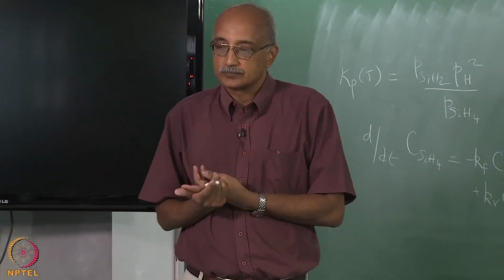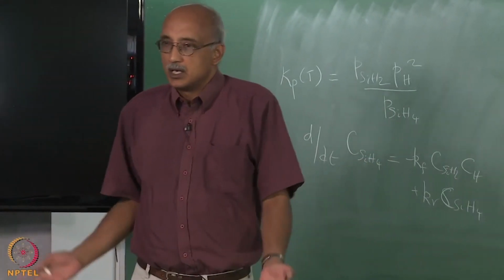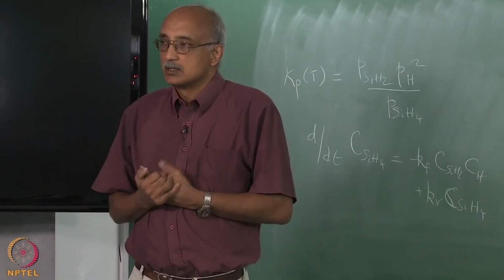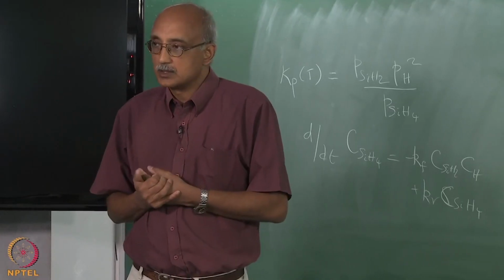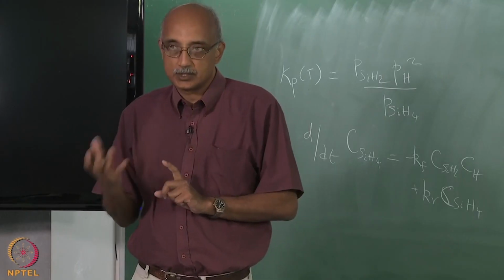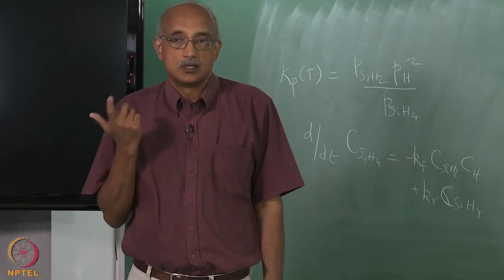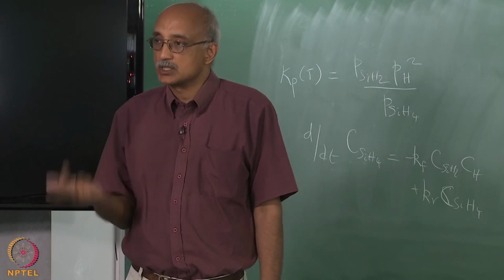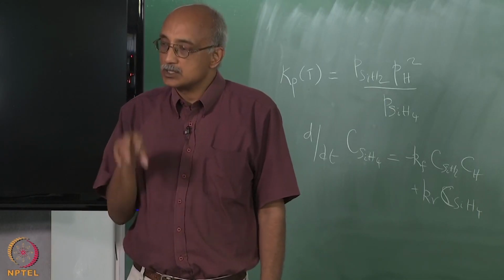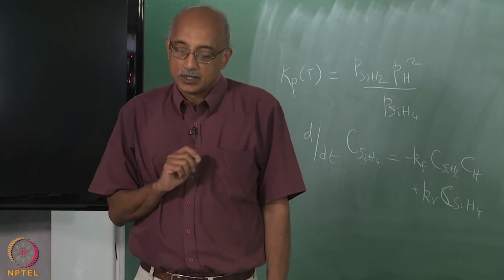So, I mean there could be literally dozens or even hundreds of these chemical reactions that are constantly going on. Even in the equilibrium case, even if you can assume that equilibrium exists, how do you handle all that? There are going to be simultaneously 100 reactions going on and rate constants that are involved, and it gets even more complex in the kinetically limited case, because you have to solve these equations simultaneously with your momentum conservation and energy conservation equations, so that you know the local prevailing velocity, the local temperature and so on, in order to be able to do these calculations.